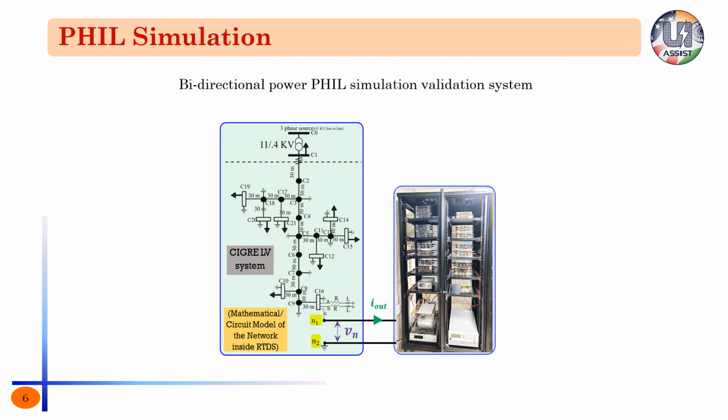In a PHIL simulation, what happens is one part, which is generally the bigger part of the circuit, is simulated in a real-time simulator, and a smaller part of the circuit, which is the hardware under test, is connected with this particular simulator, and various studies can be performed and various performance parameters can be calculated.